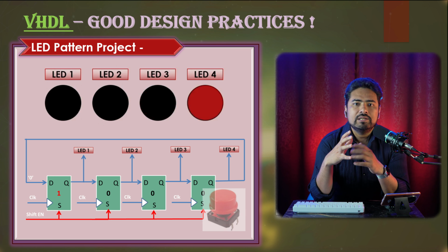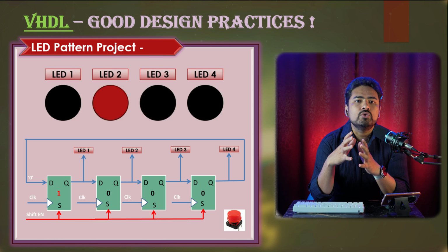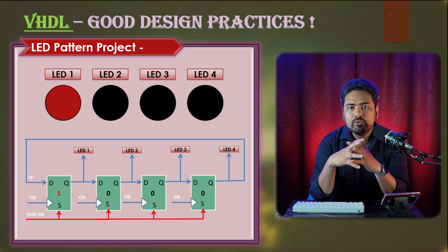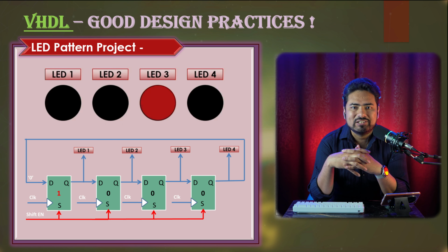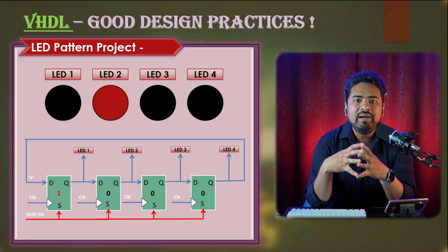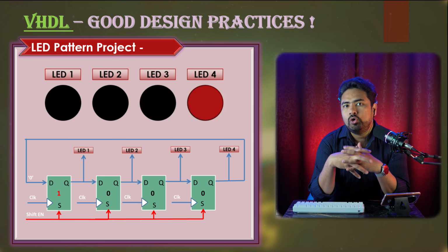Now because this switch is asynchronous in nature, we will convert it into a synchronous signal by using a two-stage flip-flop, like we discussed in the best practice sessions. And third, we will write another process to detect if the switch is pressed or not.